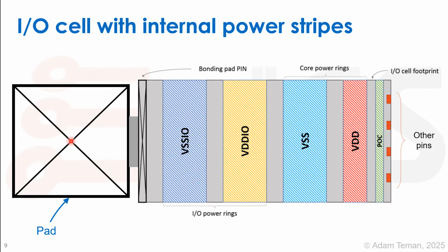So when we do a wire bond, we're not going to mechanically break this and cause an open or something like that. And so this is a pad. It's going to be different with the flip chip design. This is on a wire bond design, which we are playing with, but again, it does nothing. It's just a wire, and that's the pad itself that connects to the PAD terminal on whatever our IO cell is.